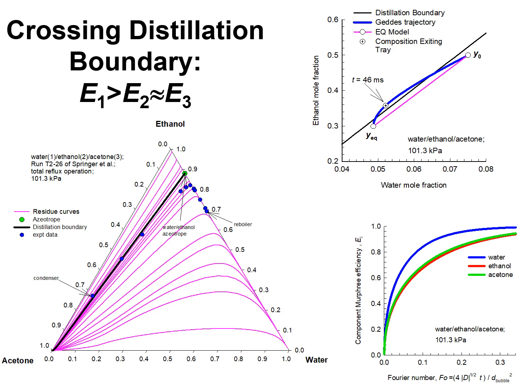The Maxwell-Stefan model calculations for a typical tray with a feed composition entering the tray somewhere here, and this is a blown up diagram showing the compositions. This is the entering vapor composition.